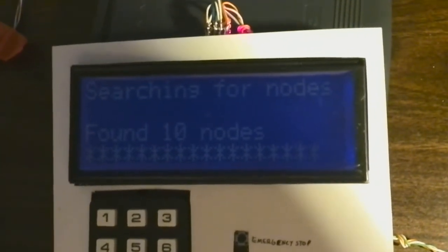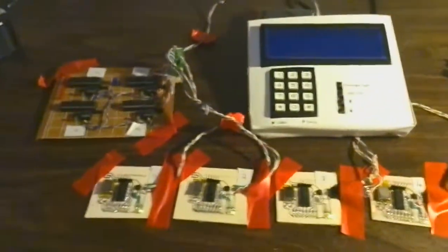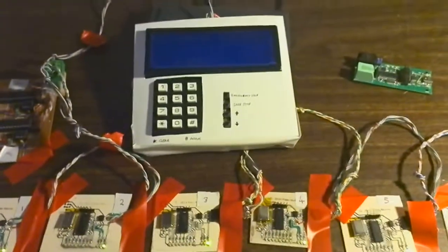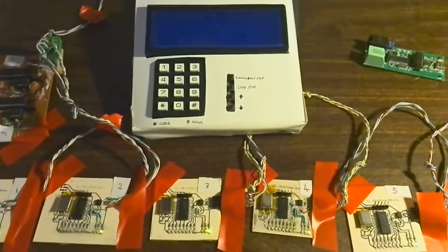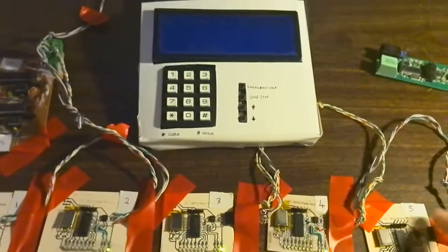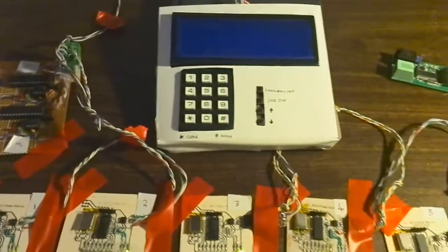Now the count and delay can be modified to make it shorter if you're not expecting too many nodes. That's something I've got to add in the future. Now currently we're using the waterfall distribution method, where it will fill up the first load bank, then spill over to the next one and the next one, and so on. And for a safety precaution, it then sends a clear to all the other load banks inside the swarm.